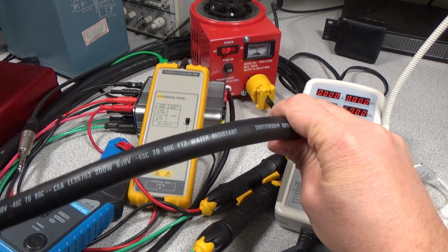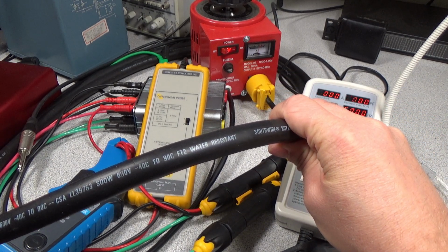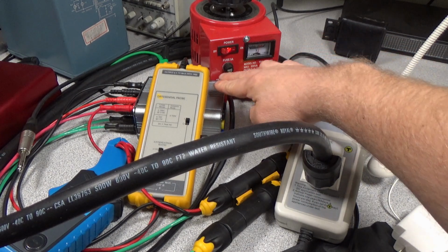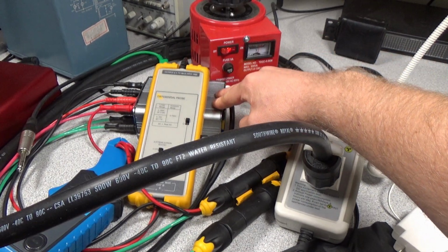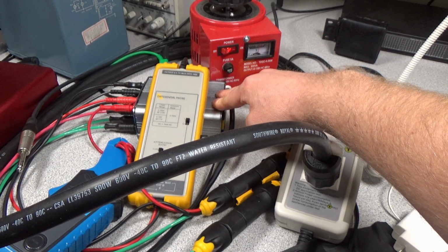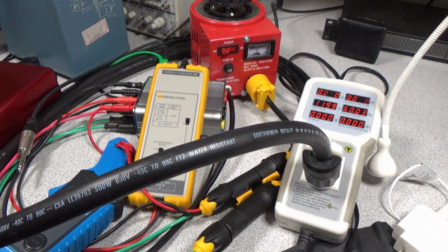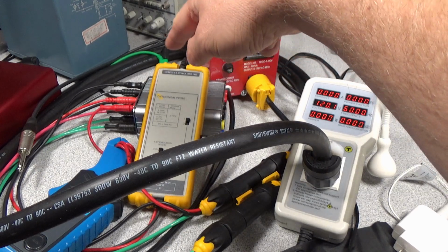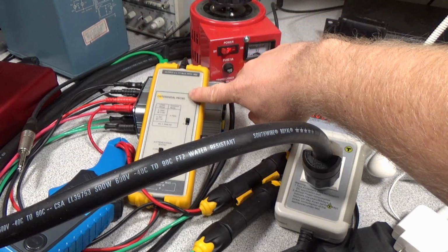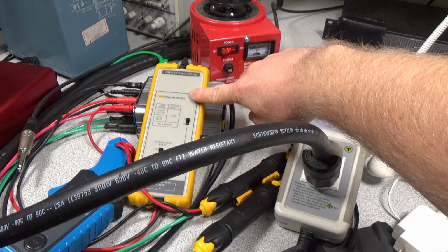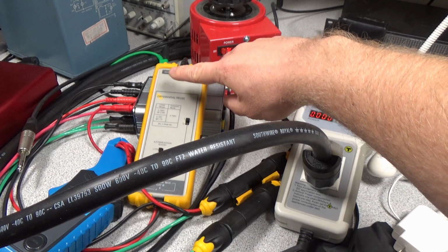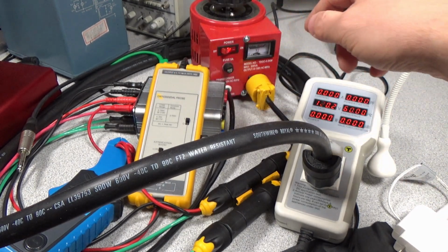So this is then feeding out to some overkill size power cords here and going into this box, which is just the connection box. It just gives us a lot of ports to be able to tap off voltages or current and things like that. So what we're doing there is we are tapping the voltage off, going into a differential high voltage probe, which is then going into an oscilloscope.